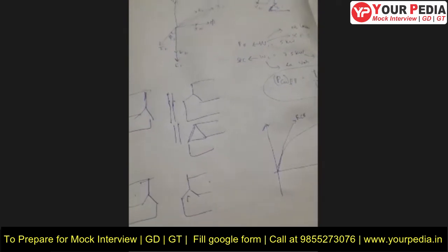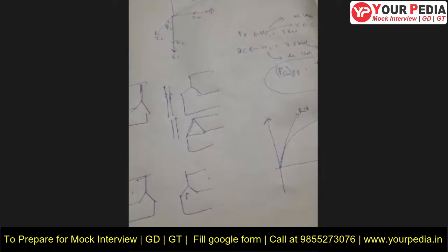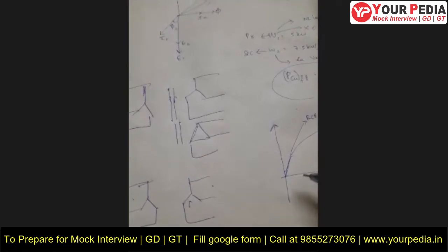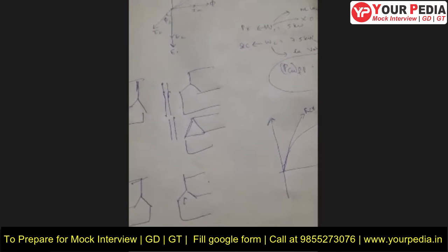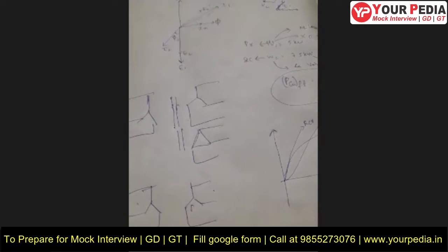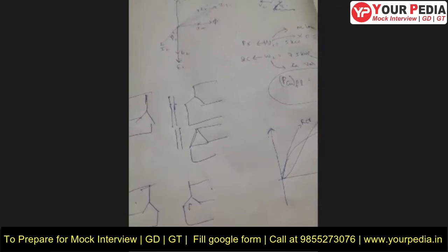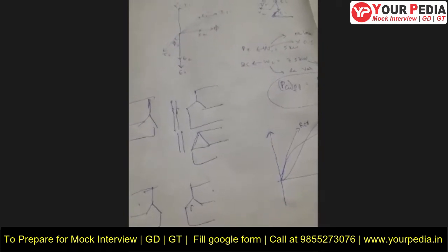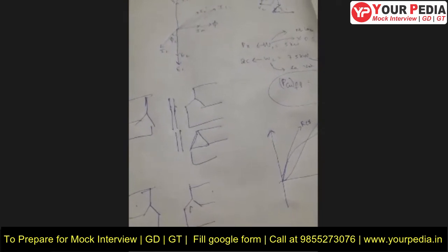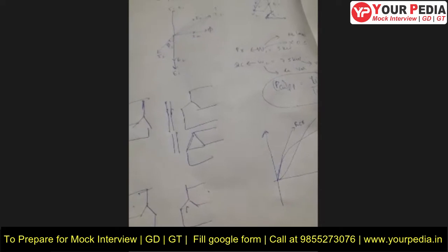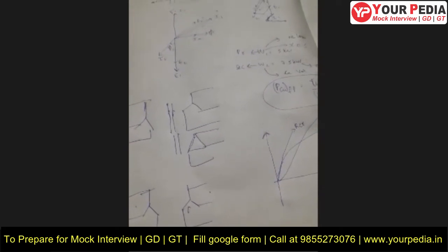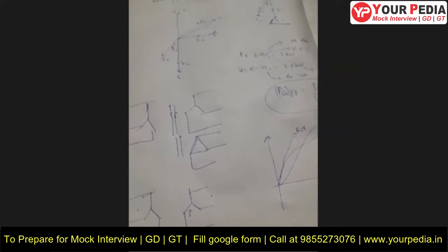Mostly this build-up phenomenon happens in a self-excited DC shunt machine, since its field is not externally excited. The EMF which is built up in the armature only should excite the field, sir.